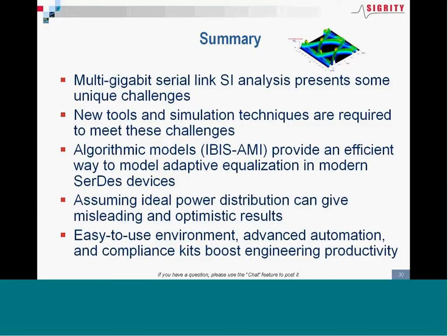Algorithmic models, IBIS AMI models, provide an efficient way to model adaptive equalization in these types of devices. Again, as long as you're able to receive IBIS compliant models from your SerDes supplier, you should be able to drop them right in and run not only in Sigrity's tool but in whatever your EDA tool is.